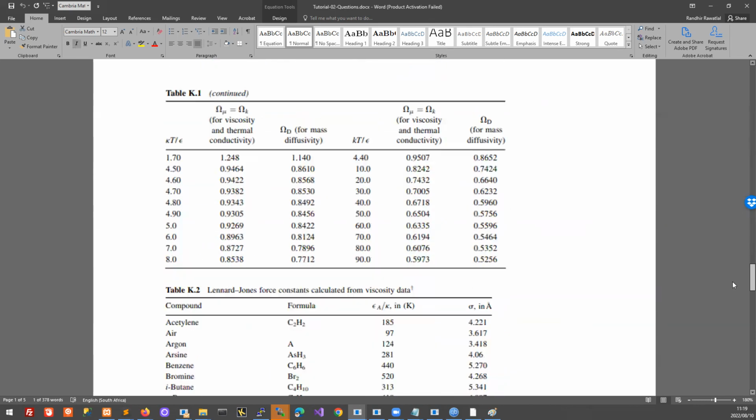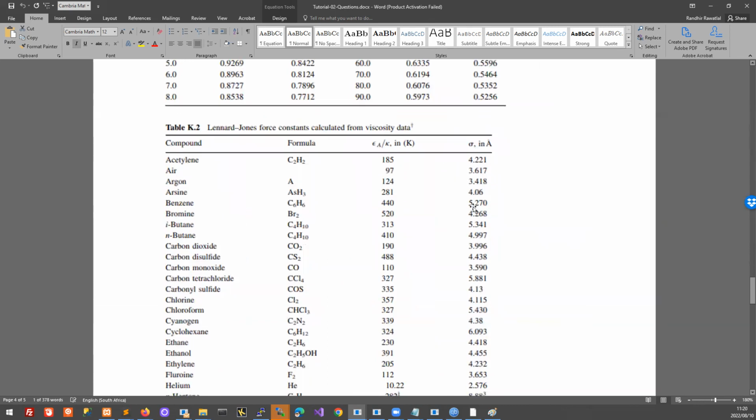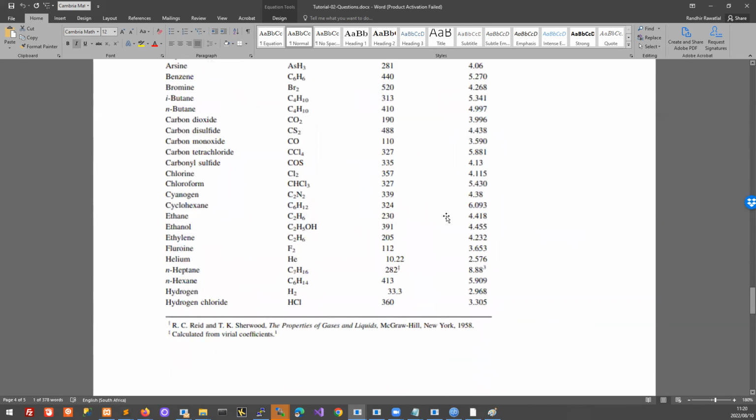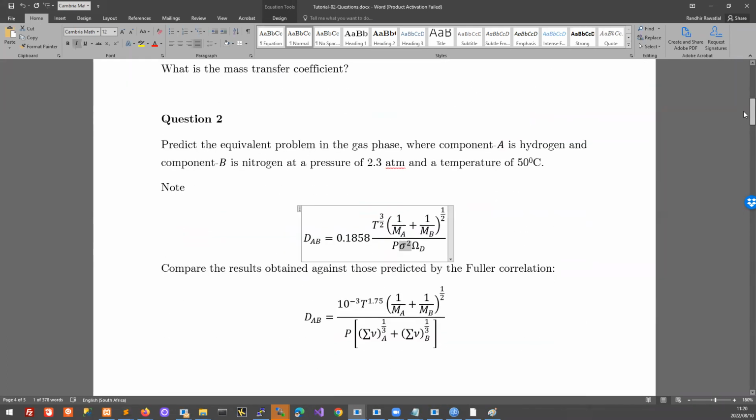It's on the same table as your Lennard-Jones constants. So you get your sigma here, and then you average that as well. I think that one is more of a geometric averaging. So just look in your Welty, Wicks and Wilson at this example. And then you get the mean values for those two. Everything else is specified, and then you can calculate the diffusivity there.